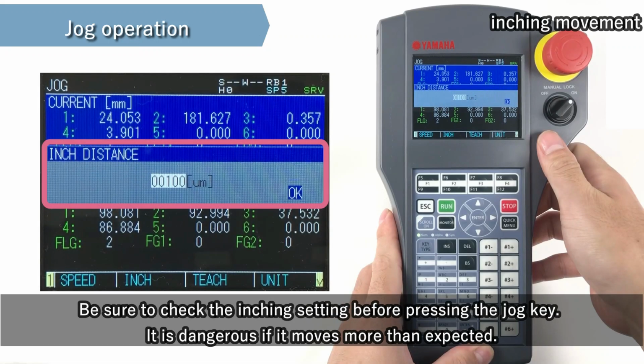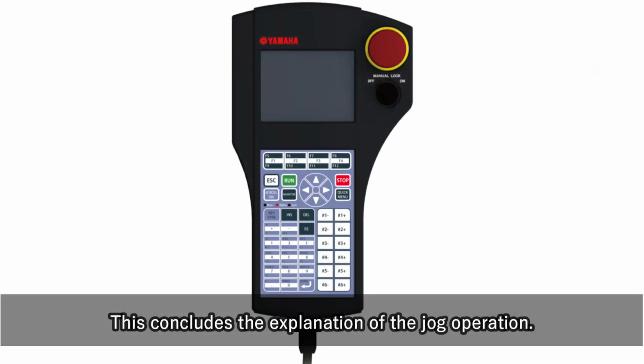Be sure to check the inching setting before pressing the jog key. It is dangerous if it moves more than expected. This concludes the explanation of the jog operation.